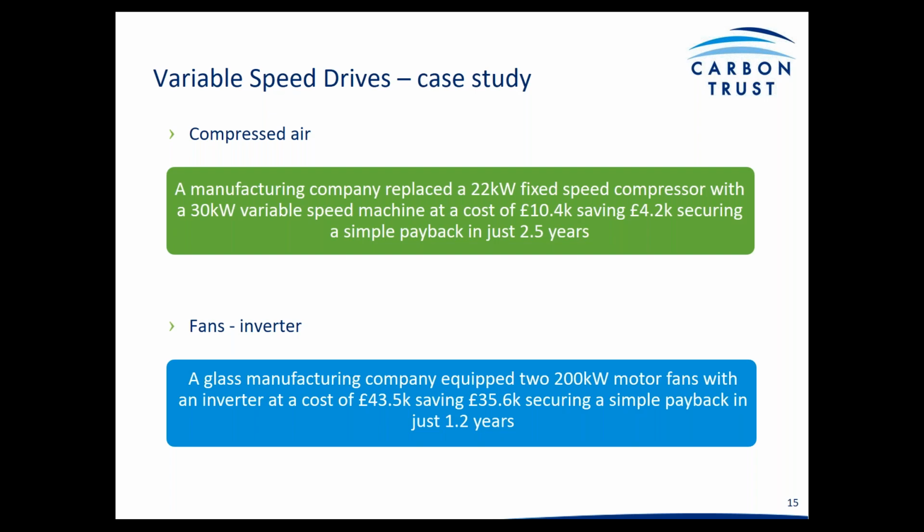Another case study that we've got here is about 200 kilowatt motor fans that have been fitted with 2 inverters, and the payback here has been really good, in the region of 1.2 years. So again, if we look at the size of these motors, 200 kilowatt, and there was an opportunity to save energy by reducing the speed, the payback is always extremely good.